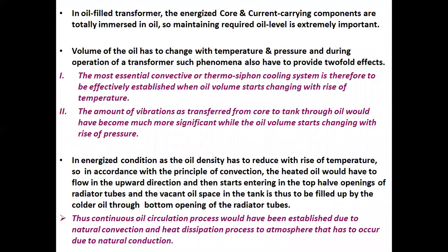In an oil-filled transformer, the energized core and current carrying components are totally immersed in oil, so maintaining the required oil level is extremely important. Volume of the oil has to change with temperature and pressure, and during operation of a transformer, such phenomenon would provide twofold effects.